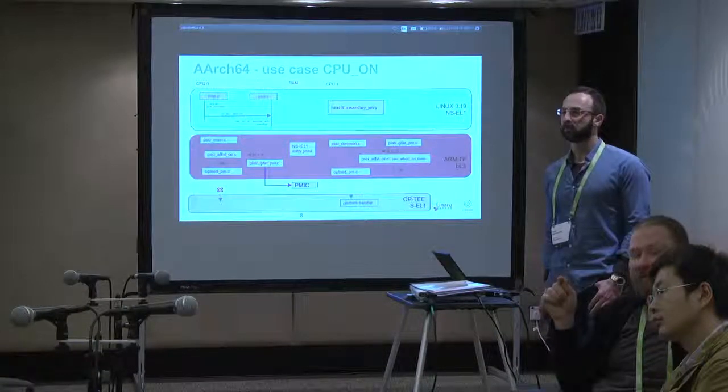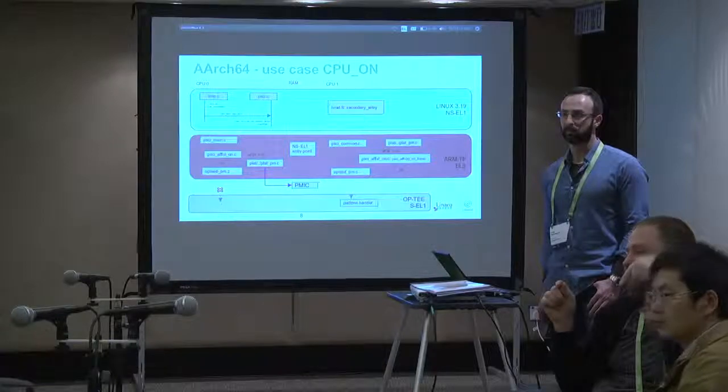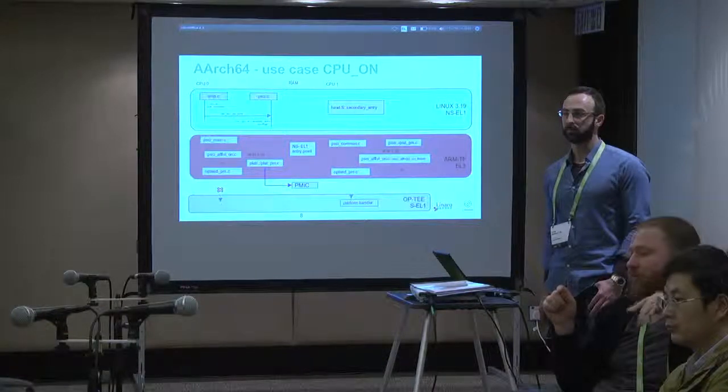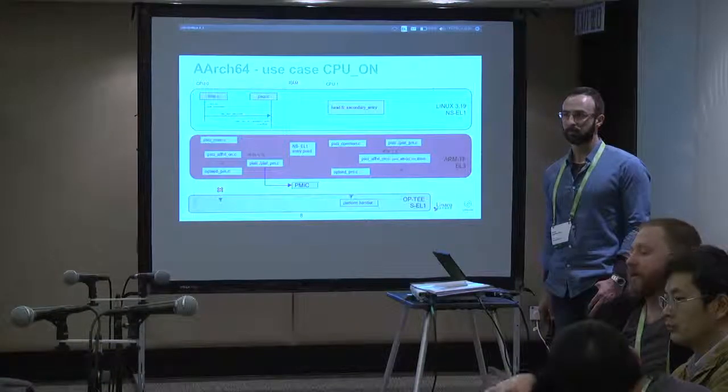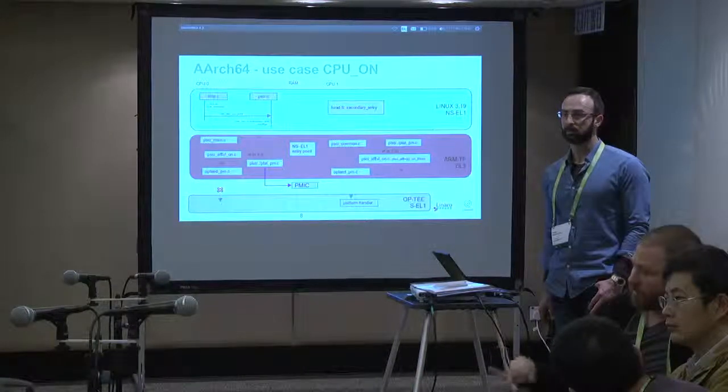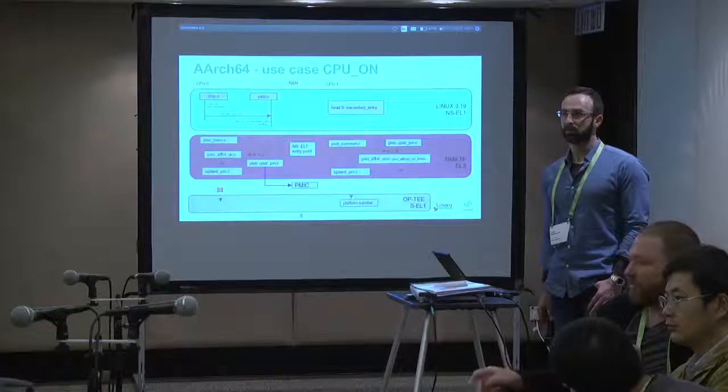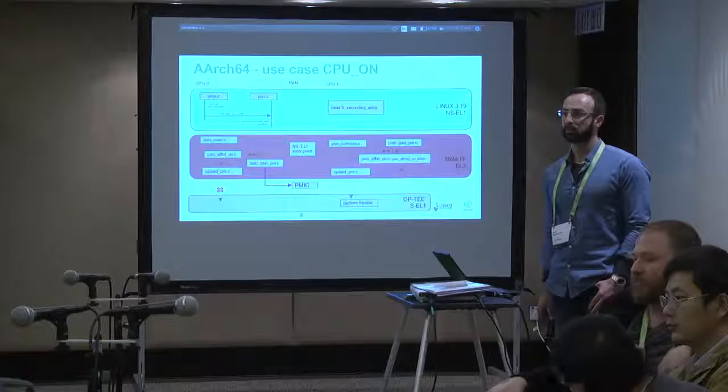I guess the point being raised here is Linux is going to want to talk to the PMIC for various reasons, maybe retention voltage, and the firmware is going to also want to do that, and maybe the kernel's doing it for device DVFS, and PSCI is doing it for CPU DVFS. No, I'm just trying to understand.